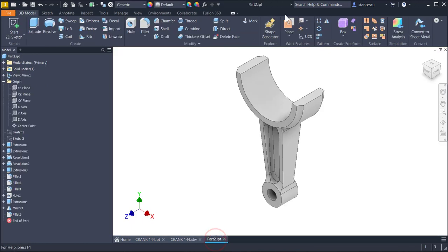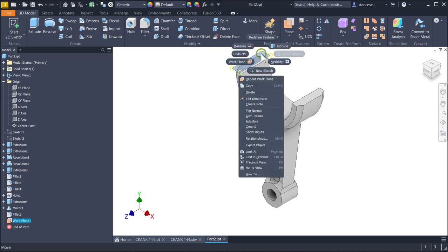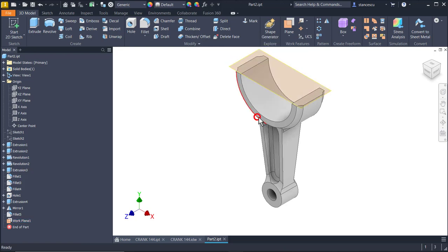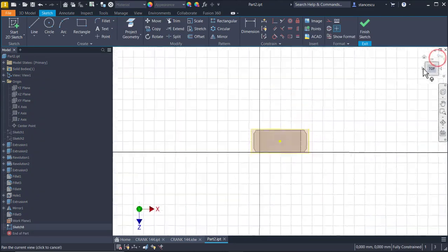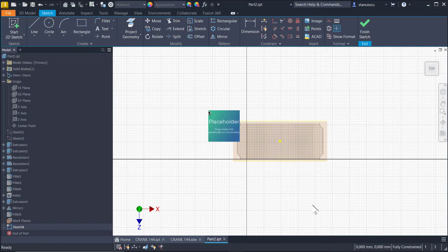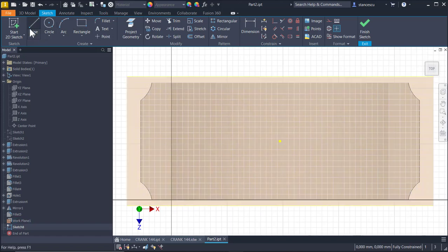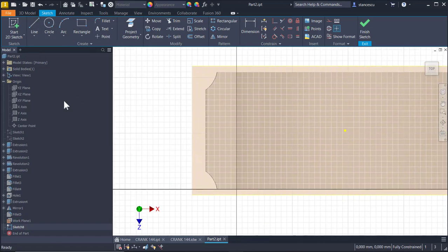We start by creating a plane with 3 millimeters altitude. This plane must be auto-resized to see better the placement. Then we create a new sketch in the plane. Let me rotate to have a better view. Then we create that contour.